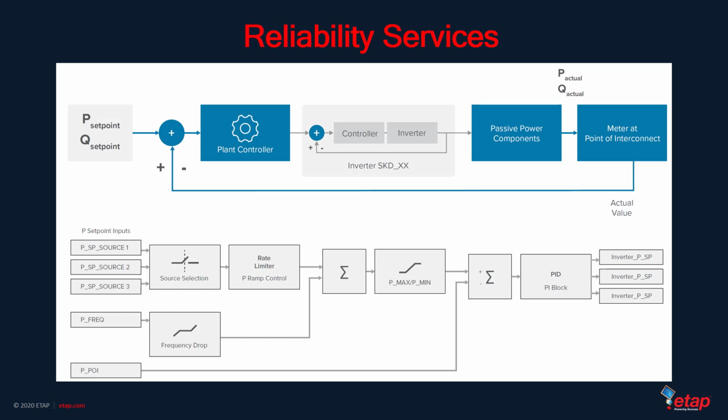Each inverter is equipped with a controller that provides localized closed-loop control based on its commanded set points. The local inverter's controller is constantly communicating with the plant controller. If an inverter stops communicating with the plant controller, it would appear offline or unavailable and be omitted from the plant control scheme. An inverter may still run and produce power even if it's unable to communicate with the controller. This emphasizes the importance of a closed-loop control scheme. The closed-loop feedback at the point of interconnection detects the unknown contribution and scales back the commanded output to compensate.